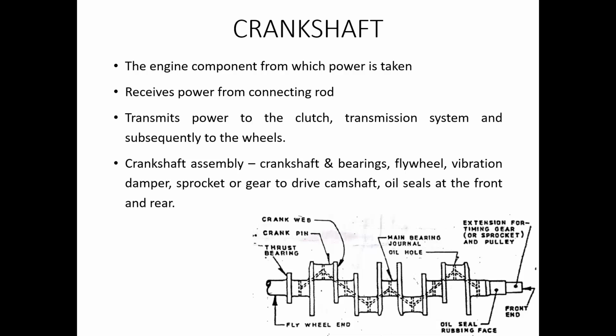And it also has a sprocket or a gear to drive the camshaft. Camshaft is a shaft which is used to control the opening and closing of the inlet and exhaust valve that we'll be seeing later on in the slides. And also oil seals at the front and the rear. So all these are the different parts of the crankshaft assembly, and all these are usually integrated together.